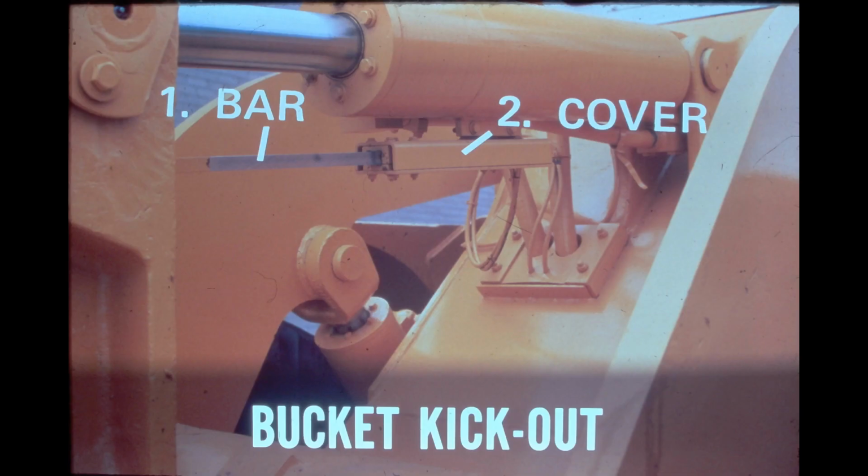This photo shows the air release mechanism attached to the bucket cylinder. As the rod extends to roll back the bucket, the bar on the mechanism also extends. At a preset position, an air valve lever, located under the protective cover, moves and sends air to the bucket detent to release the bucket spool. The position of the air valve is adjustable.